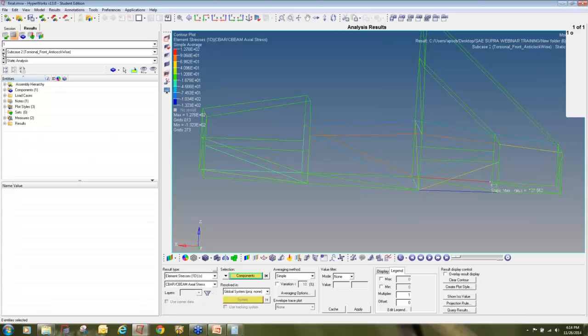Similarly, if I change the value, it goes to the second half for the anti-clockwise. For bending, these two blue regions are not taking any forces. Then torsional rear, then bending. In bending as well as in torsion, this member is coming as the weakest member because the maximum stress value is coming here. So bending front anti-clockwise, then bending rear, and bending rear clockwise and anti-clockwise.